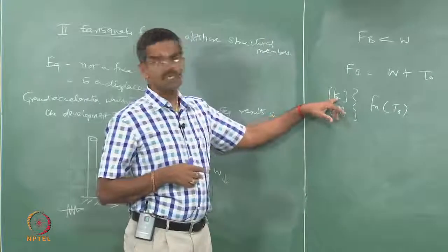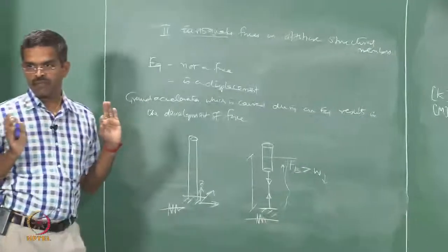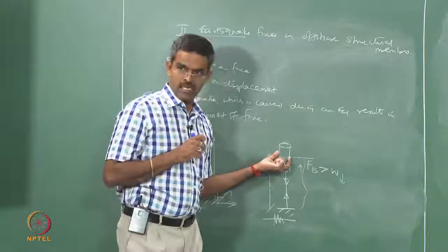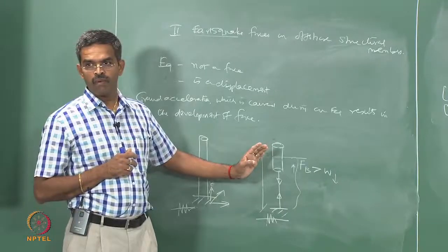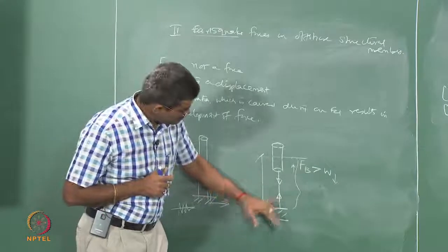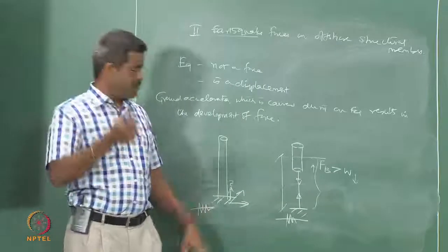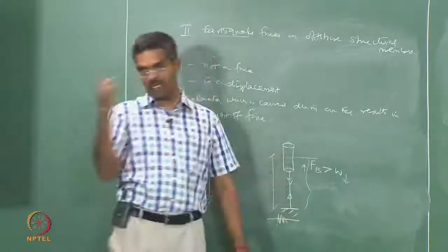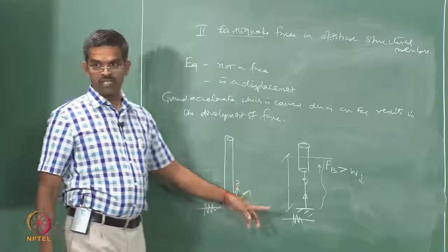When the stiffness matrix changes, the frequency of vibration of the whole system will change. When the frequency of vibration of the whole system changes, it may get into a mode of resonance with the wave. Therefore, tether tension variation is indirectly an accelerated problem because of earthquake force happening at the bottom, though it will not affect the superstructure directly, as in this case. So, this is more serious, one reason.